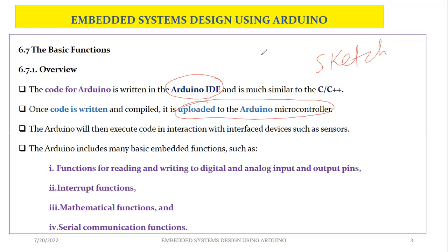So for the digital pins, we can configure to use them as input or output, especially those which do not support PWM, but for the analog pins, we can only employ them as input pins.